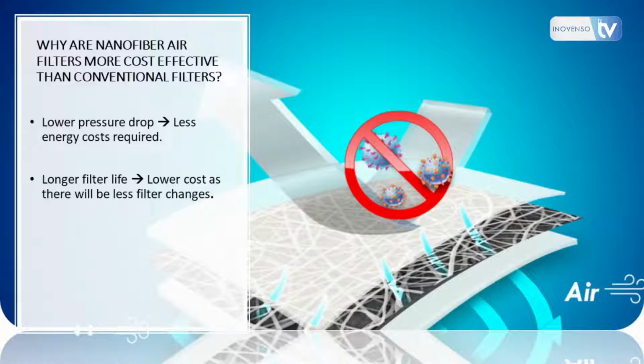Since these have low pressure drop, when the filter needs to be cleaned with a backward repulsion, the particulate matter doesn't get stuck in the middle. So it has an overall lower pressure drop, and the particulate matter does not cause any blockage, which is common with normal air filters. These blockages cause the filter over time to stop pores, and that degrades the quality of the filter, so they need to be quickly discarded. With nanofiber filters, they don't really have such a problem because they don't have this depth filtration issue. So overall it has longer filter life. You don't have to discard it as quickly.